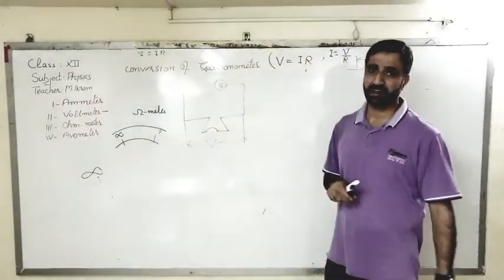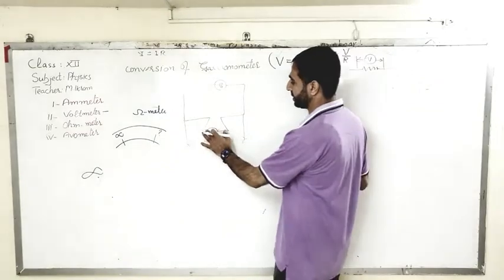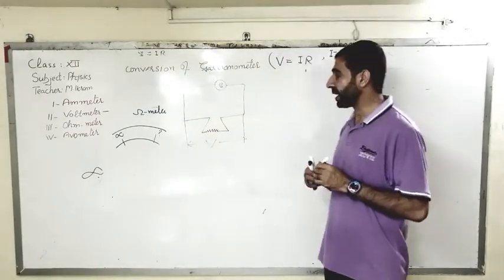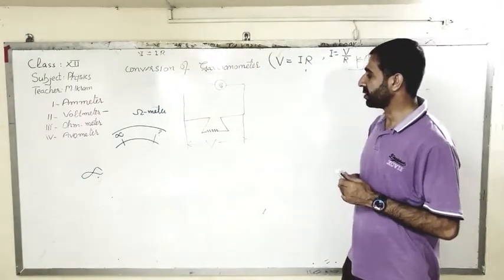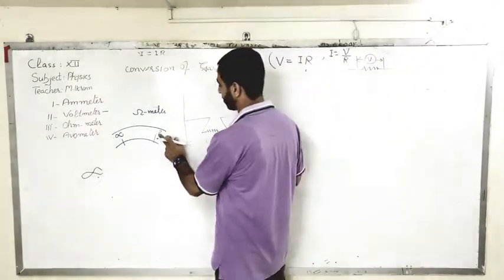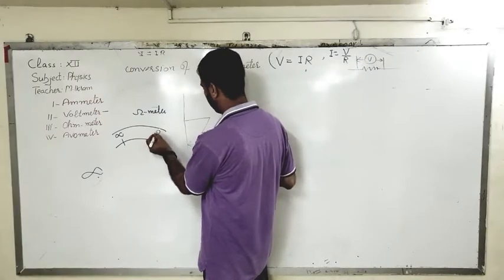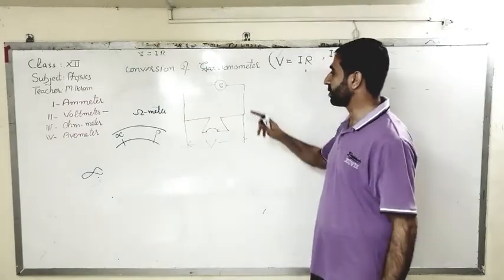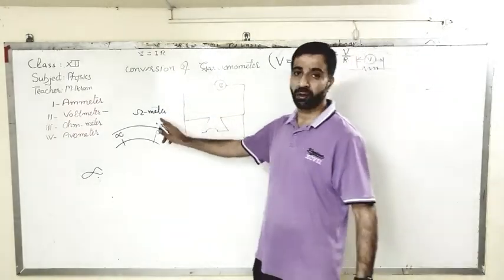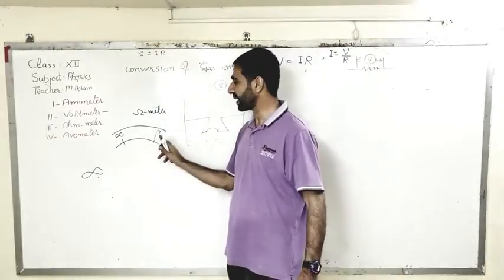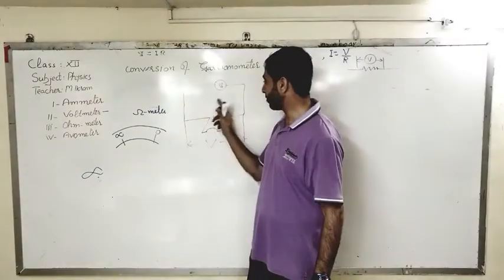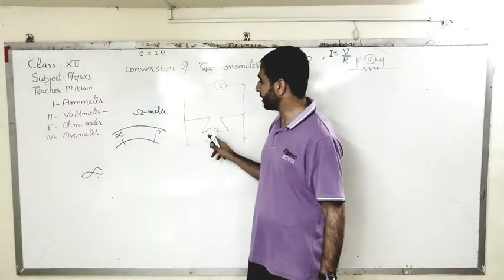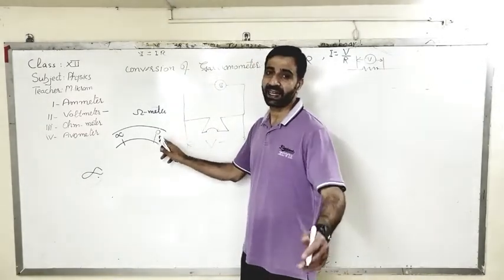And now we will do this for zero resistance, and we will mark it as 0, right? Why? Because if you just make a short circuit, then what will be the resistance of the path? 0 ohm for the maximum current of the galvanometer, right? Maximum current will pass through the galvanometer, and since it is a short circuit, there is no resistance, and we will mark it as 0.